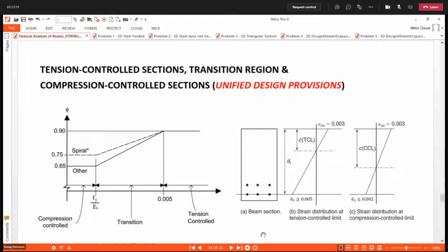That is why you see some structures collapse even though they have a lot of steel. It is because the concrete and the steel in tension need to work simultaneously. So that is about this diagram, so that at least you can see, when computing, how they differ in the determination of the depth of the neutral axis.